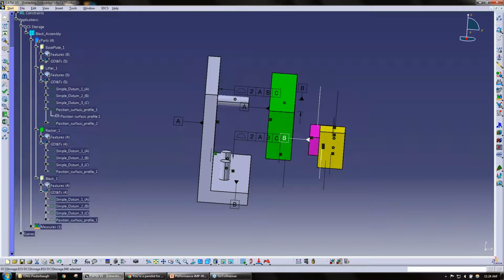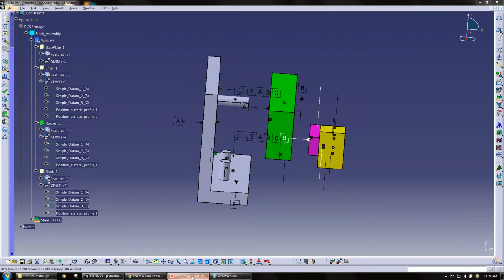If I recall correctly, it varies the tolerances first and then the GD&T. So if you have a feature size tolerance, your GD&T, if it's got bonus, will actually pick it up. Unless it's vice versa. So check first.